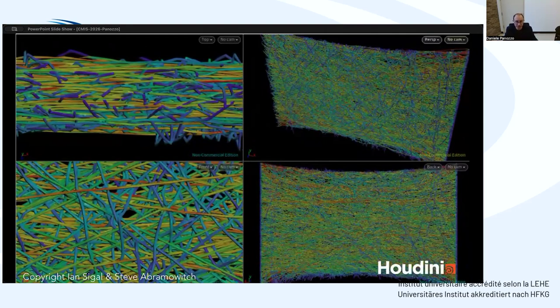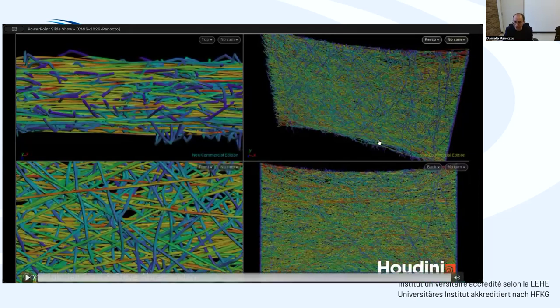And what it turns out is that the errors are around 20 to 30% on displacement, which for the complexity of this is pretty insane. And the curious observation here is that the material model that you use is not so important. Most of the interesting material behavior here really appears from the contact and friction interaction between the fibers, which was kind of unexpected. Again, in a case like this, you have millions of contacts per frame. So whatever algorithm you use here needs to be extremely reliable if you want to hope to make it to the end of such a simulation.